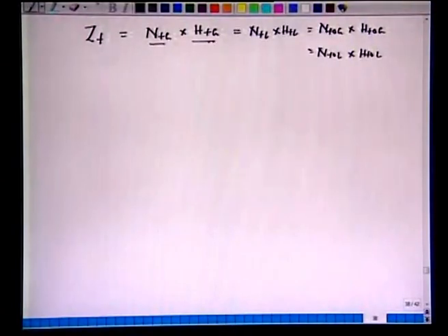We have to be careful, you read the problem correctly, what are the quantities which are given to us, because you have to do these integrations for NTG, and you have to calculate the height of a transfer unit based on the mass transfer coefficients. In principle, any of the 4 equations will work and should give you approximately the same results, within numerical error. So, here if you recall, the individual mass transfer coefficients for the gas phase and the liquid phase are given to us. So, we should make use of and work on this NTG and HTG. Okay. One can still work on NTOG and HTOG, but the computation will be slightly more cumbersome.